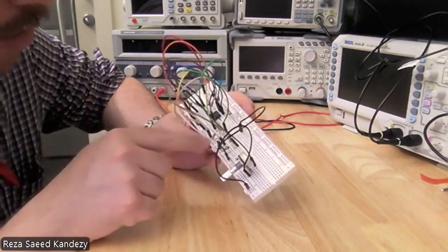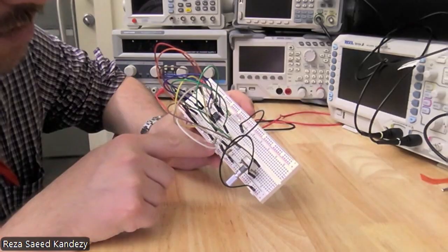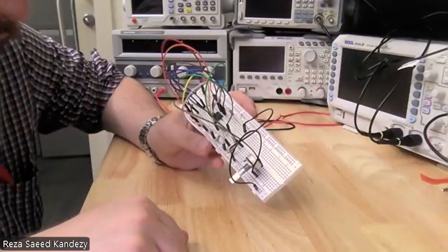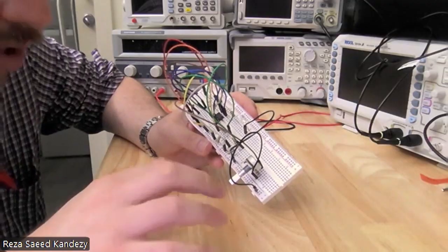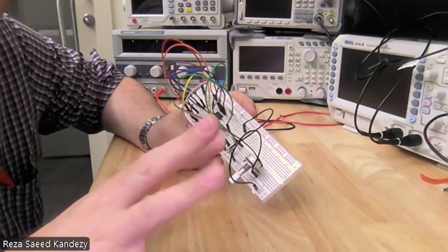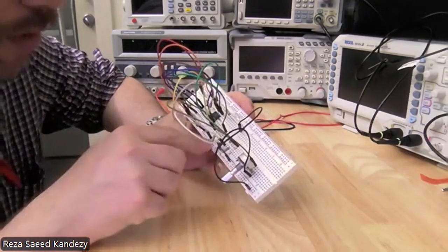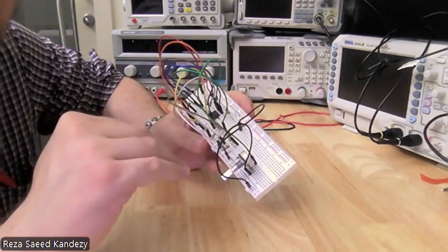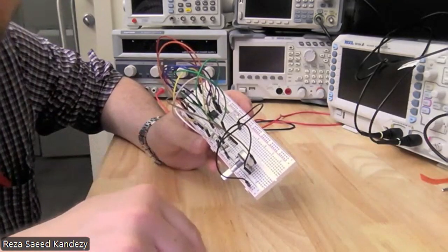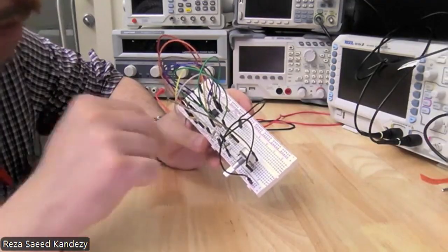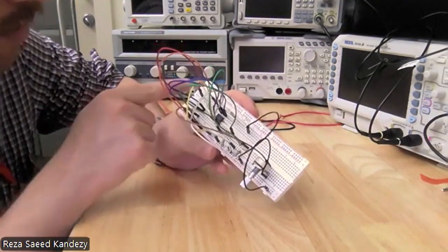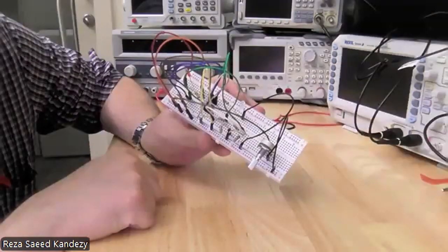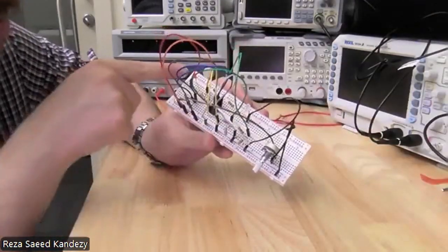Now another one is a 600 ohm and a 1 kilo ohm, which defines the voltage division when you apply 5 volts, around 3.2 volts. So my threshold for indicating the hot temperature is 3.2. So 2.5 warm, 3.2 hot. And it's connected to the op amp that is activating the red LED. You can see, I think this is the yellow LED and this is the red LED.